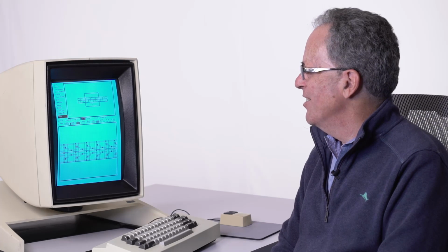The standard back then and the standard today is GDS2. It's a format that was developed 40 or 50 years ago, and for reasons unknown to me, it's still the one being used. So you would output it to that. You could then hand that file to any company that is capable of making masks.